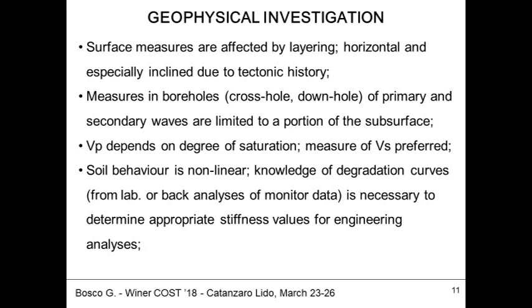We have typically used downhole tests to get a measure of the stiffness of the material. We are talking obviously of stiffness at very low strain, the strain connected to a wave propagating. This should be supplemented with laboratory tests to determine degradation moduli and so on, which are obviously difficult to execute.